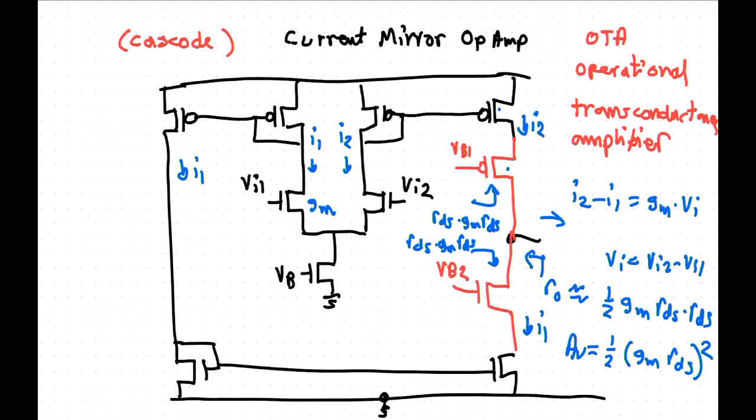Now, what makes it operational is that, just like an op-amp, you are normally using this in feedback. Very often on chips, you don't want to use resistors in the feedback because, one, the current flowing in those causes power dissipation, and also it means you've got to make your amplifier able to drive these resistors, and that's often not necessary.